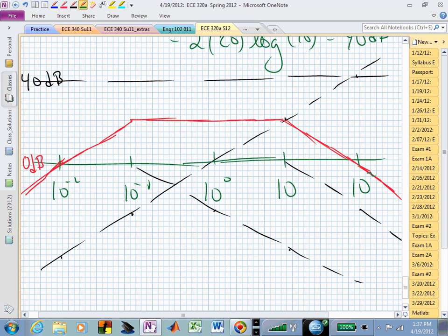And this is what will happen if you have quadratic factors. Now you have this 2 factor, and you will be sloping at 40 dB, either plus or minus, depending on whether it's a 0 quadratic or a denominator or pole quadratic.